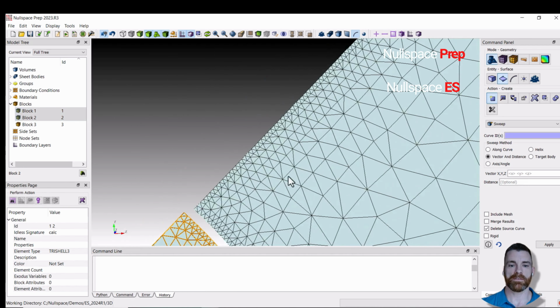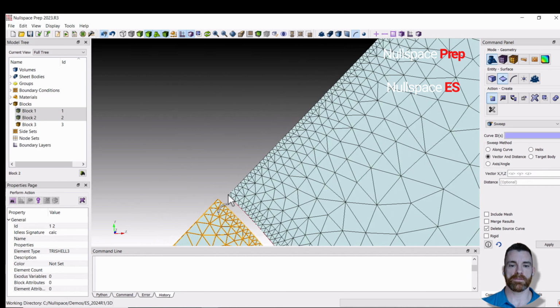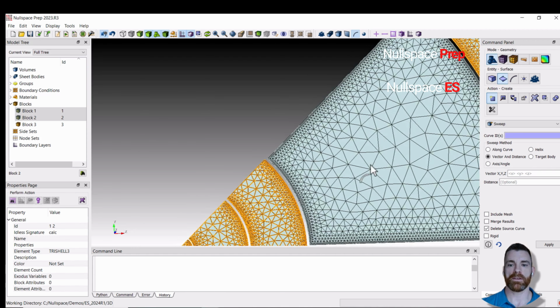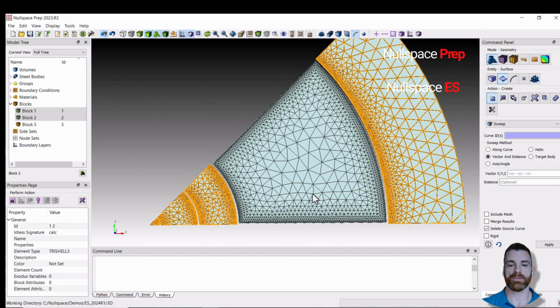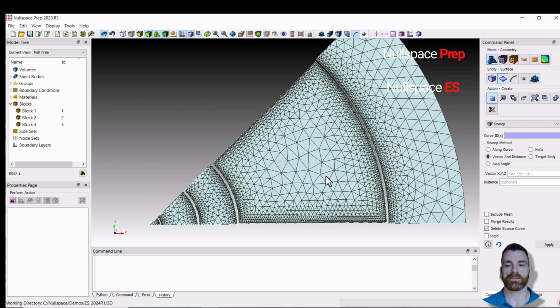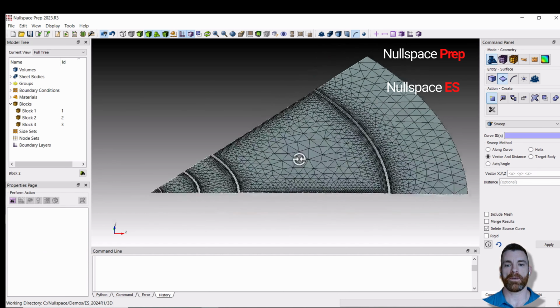And then we can examine here this DC electrode. There's a gap, so half the gap width at this symmetry plane is represented, and of course we want to have a fine mesh there on the edge. And this is a good example again of how you can leverage the even and odd symmetry capabilities to be able to synthesize arbitrary DC electrode pairings. So we can run this trap with this 8-fold rotational symmetry in even and odd modes and still have flexibility in terms of how we synthesize DC electrode values.